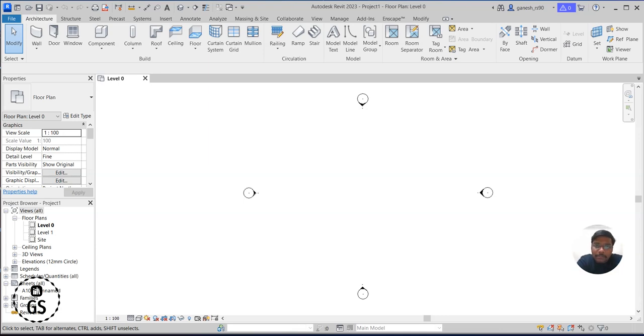So, massing is basically to make a model or some kind of user-defined shape. So, if you want to make some unique designs in a model, then we can go for massing objects. In order to start massing, first of all, we need to set a work plane. Work plane is an important concept in Revit. So when you want to do some massing object or a part, you create a work plane, select the particular work plane, and then you can start your model making in these objects.